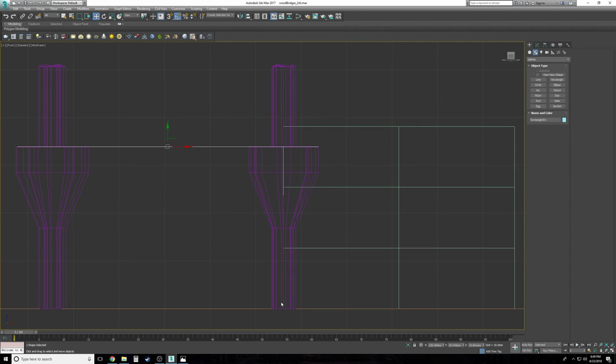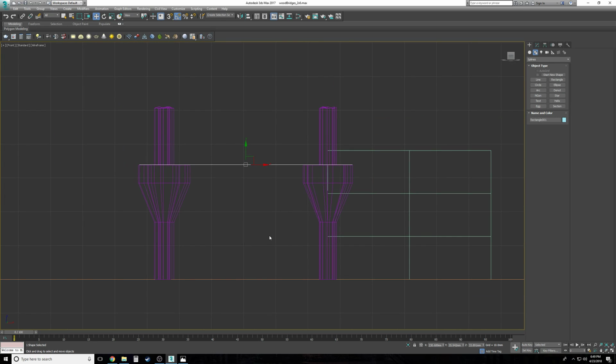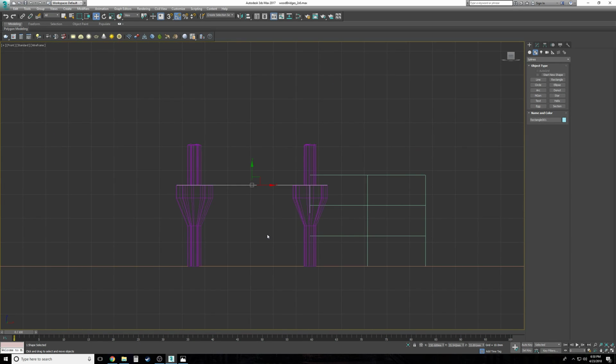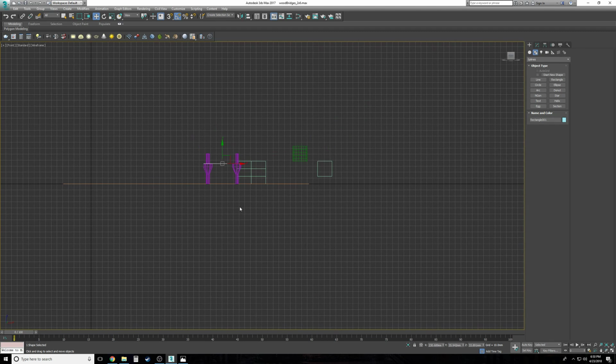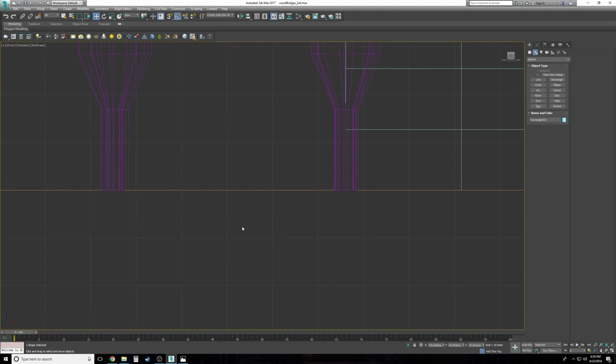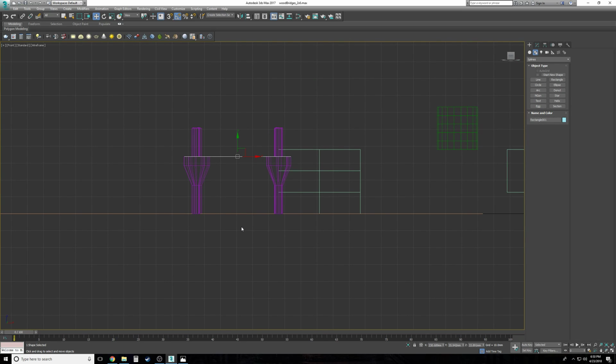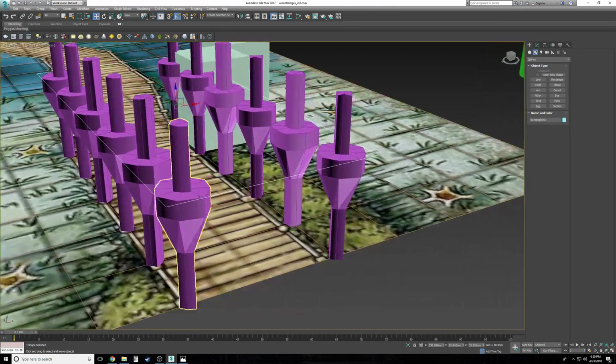Now, the problem is I've got this thing cranked up to the top here. See how high I've got it up here off the Z axis, which is where the plane is right here. It will automatically put the object on the plane at 0. If you make any other objects, even though this object is up here, it will put another piece down here and it'll make it one object, so that you'll have the spline up here and then you're going to have a spline down here that doesn't line up very right. So cancel out your height before you make a new spline. I'm at 33 millimeters. Click it on just the Z so it goes back to 0.